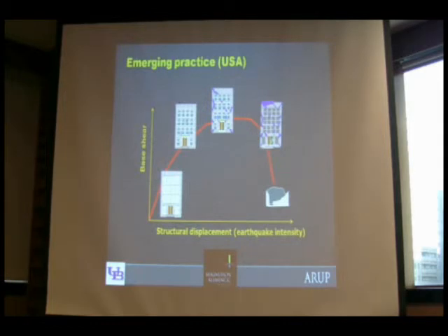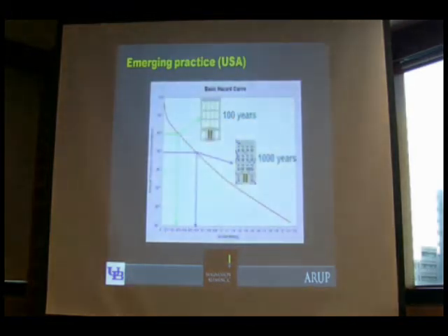For an increased level of earthquake shaking, we might look to immediate occupancy type performance. As we increase the shaking a little more, we get to the third performance level of life safety. Here we have the performance level of collapse prevention, and as we move beyond collapse prevention, we have structural collapse. But these are the four performance levels that you'll find identified in the documents referenced earlier.